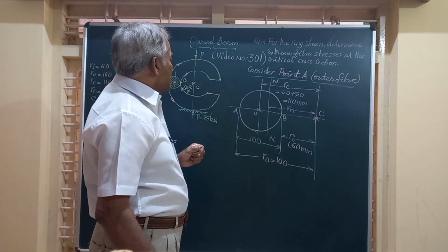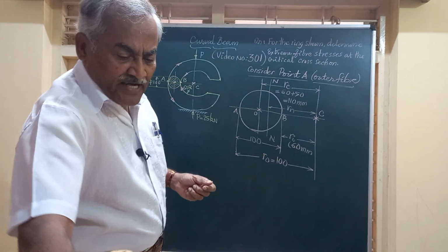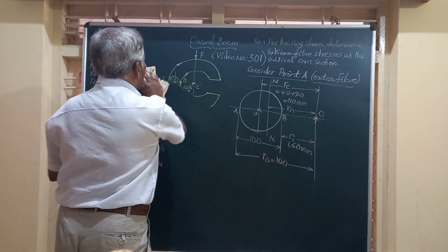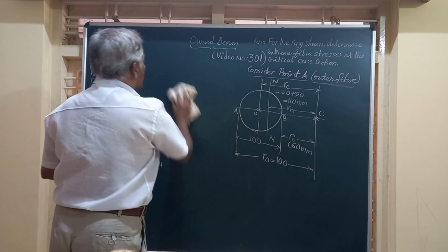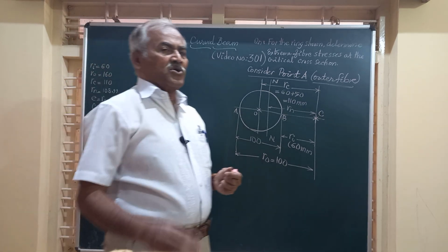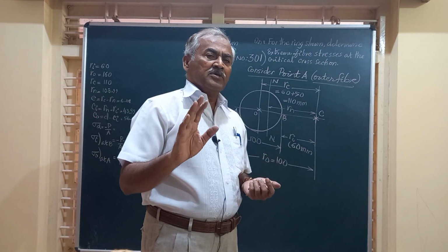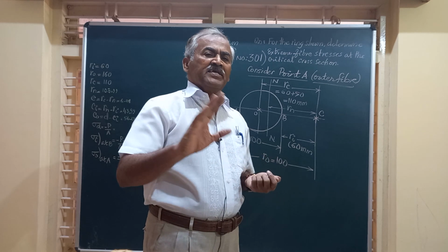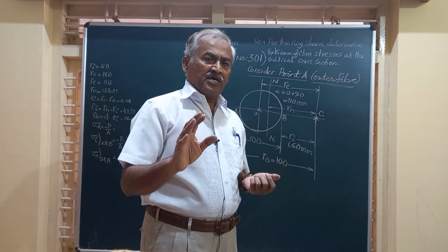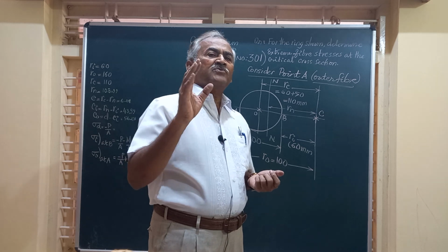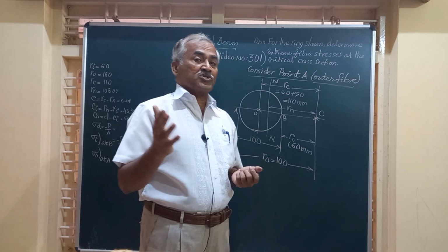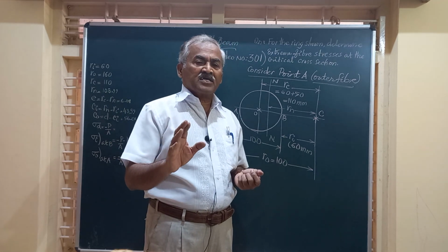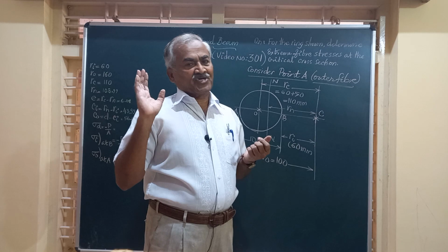Friends, this Rn is obtained from the machine design data handbook, and there is a table which will give you the value of Rn for all types of cross sections used in curved beams. I have told you in one of the previous videos, the various cross sections are circular, rectangular, then we have trapezoidal, which is the most common type of cross section used in crane hooks, curved beam. Then we have the I section and the T section.